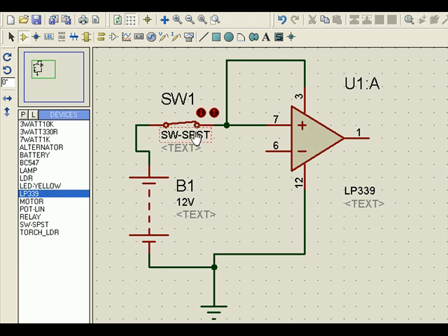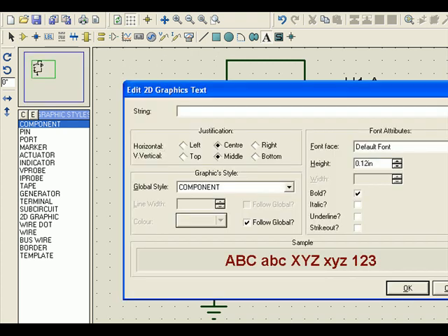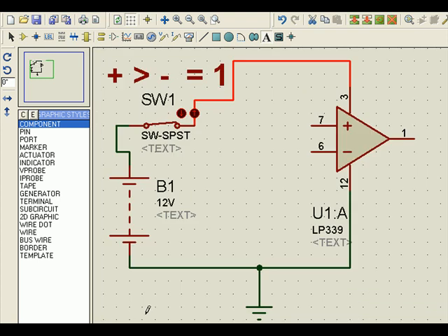And then we know that operational amplifiers can also be used as comparators. So, what we were talking about: an operational amplifier has one non-inverting input, one inverting input, and one output. Such operational amplifiers are available in ICs, either one, two, or four operational amplifiers in an IC. For convenience, we have taken one of the four operational amplifiers in an IC called LM339. Now let's see how it behaves when we start using it as a comparator.